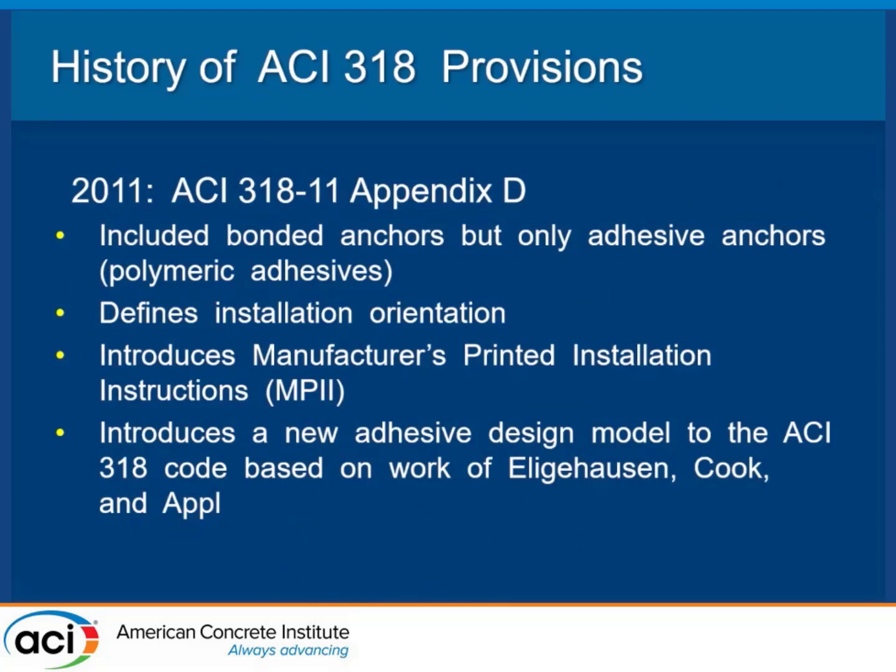So that said, we get to 2011, and we had not had anything. We just had mechanical anchors that came into that code. We had not had epoxy anchors, and of course, after 2002, or just around there, is when the Big Dig thing happened, right? That was an adhesive anchor failure, and the National Transportation Safety Board said, hey, you guys need to solve this problem now.